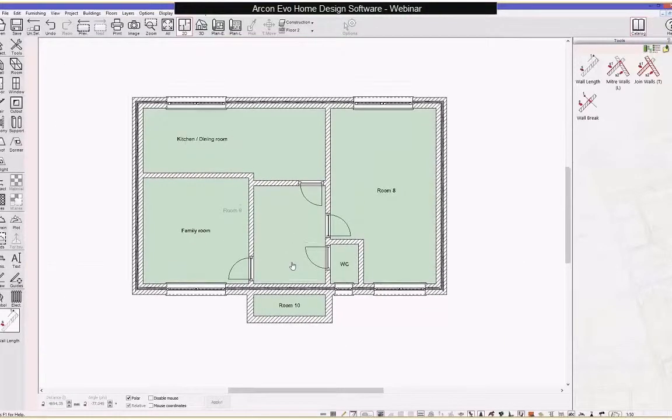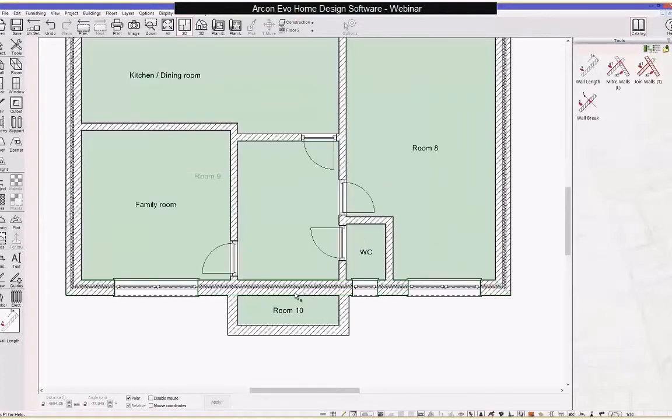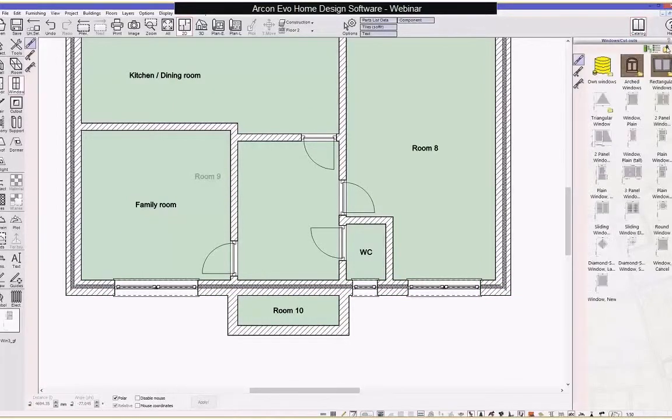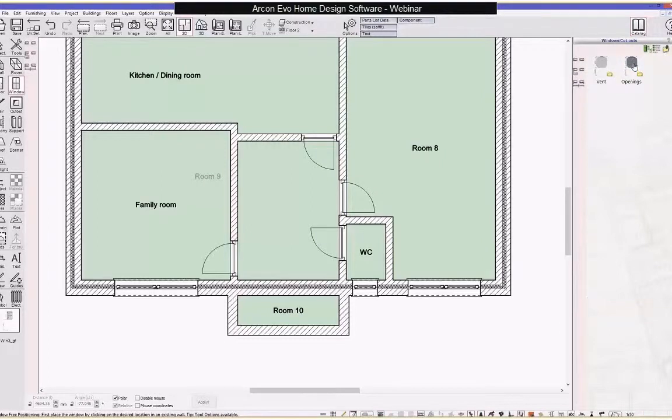Okay, and I'm going to create a cutout within this interior wall here. So I'm going to click on the Windows folder here, and then go to the cutout section. Go to Openings, and I'll click on this arched option here, and place that in position there.